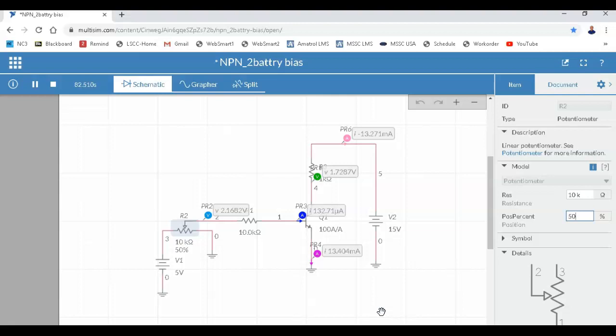What's the formula for collector current? IC equals, not times. There's no times. It's addition or subtraction. Minus. Remember, and this is what you remember: what is the biggest current in the transistor? The biggest current in the transistor is the emitter current, right? Because the emitter current is not only supporting the collector current, it's also supporting the base current.